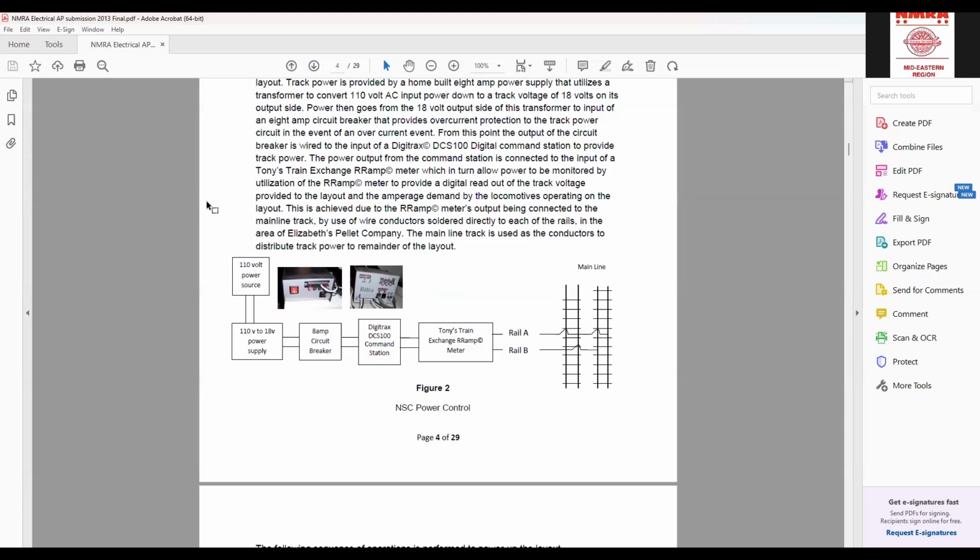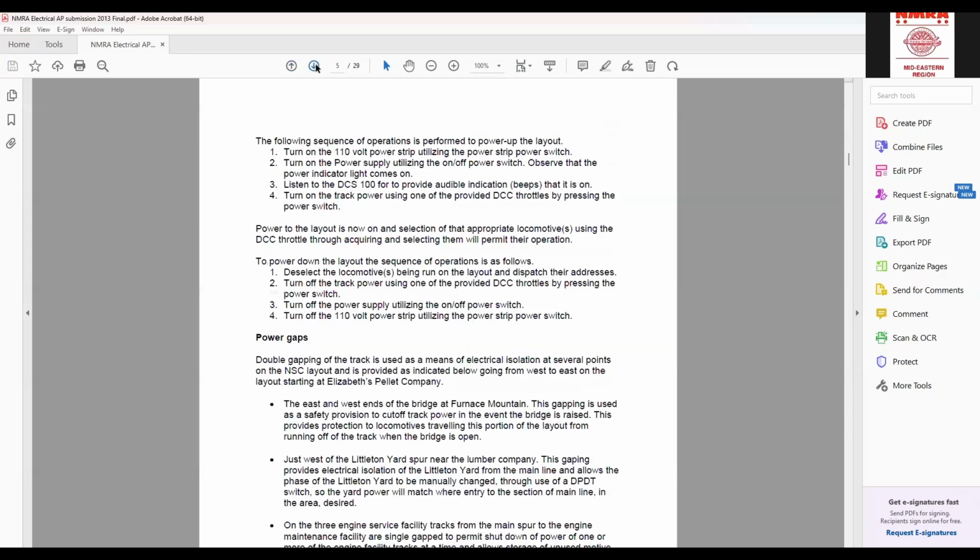And I wanted to know if I had track power on or not. One of the things you have to realize is that with DCC, as an example, you can have power out there. You've got a sound locomotive, you hear sound, the lights are working, but it won't move. That's because your track power isn't completely turned on to get that LocoNet, so it's sending commands back and forth. So I talked about how you turn things on.